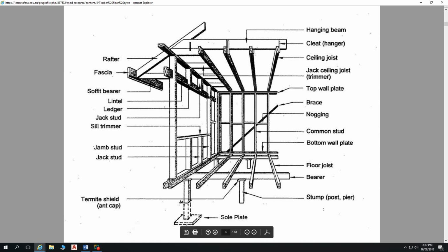But with your flooring, actually no, I said 600 centres. Sometimes with some sheet flooring, it's done in increments of 450, so 900 sheets as well for some flooring systems, but we're talking those increments of 150 millimetres still, and it's important to observe that. So what I'm saying is, you don't just set them out at 470 or 580 millimetres or something like that. They have to be in increments that suit your flooring system.